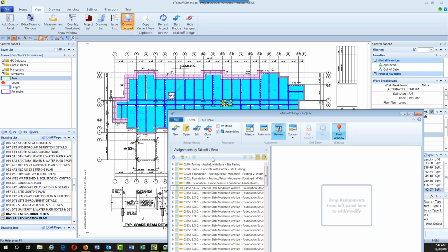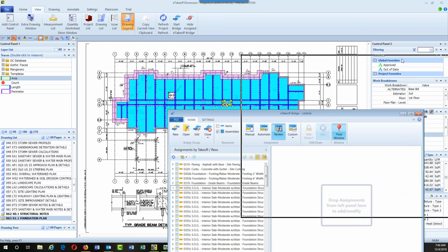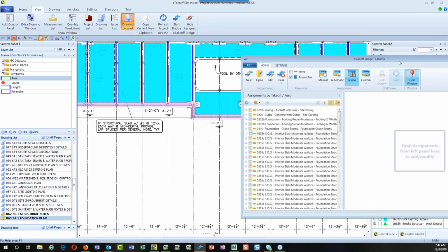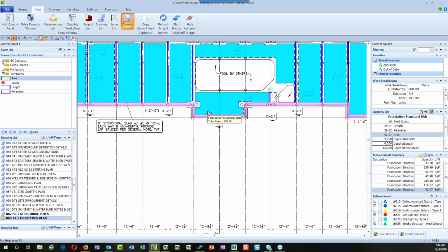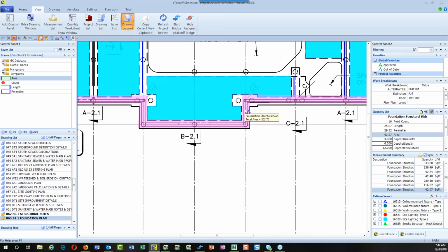How do we handle that? But before we go over there, let's say that this drawing changed, and what I noticed on this here, let me go ahead and reduce this down here. I'll bring it back. That they've decided that we need to actually put this on piers. The soil test came back, and we've got to put some piers on here. We can't just put this in the dirt. The soil's not suitable for that. It's a 3-story building, so we need to put these piers on here. So I've got to add that to this part of the estimate. It wasn't in the first part. I now have to add that. So let's do that.